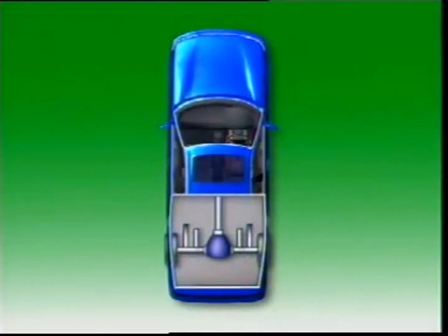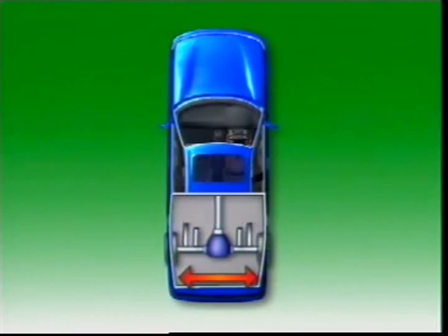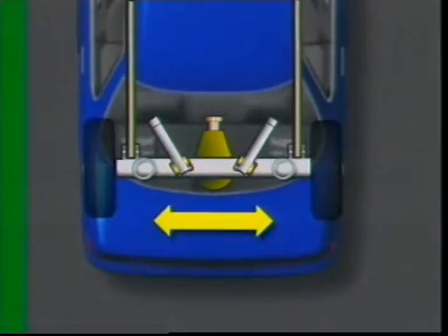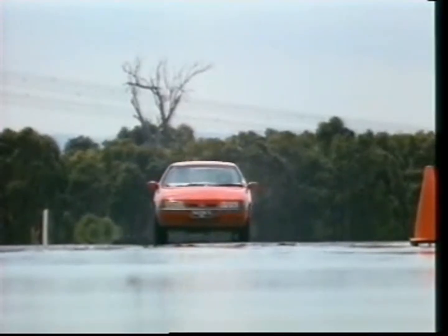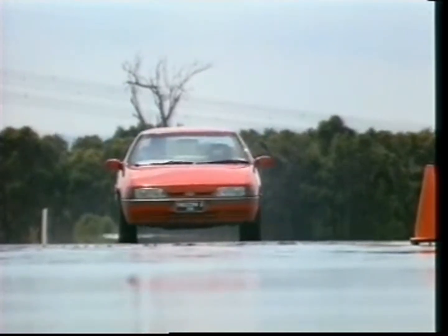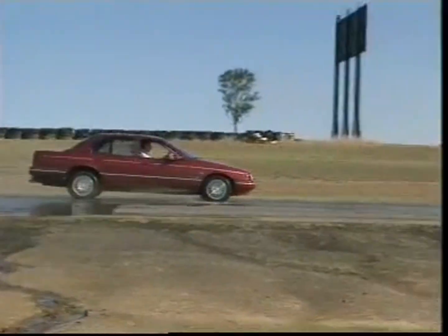They would allow the axle to move laterally if it were not restrained. Any such movement has to be controlled to keep correct alignment with the front wheels and the vehicle frame. This suspension system uses angled upper control rods to limit lateral movement of the rear axle during cornering. They also absorb the torque reaction forces, which limits rear axle wind-up during accelerating and braking.